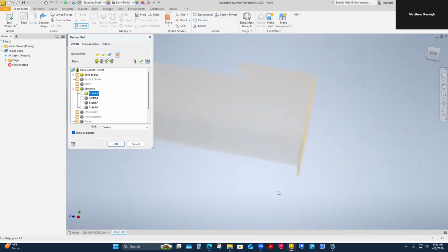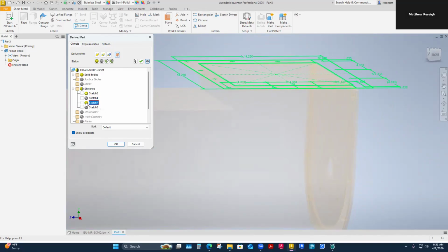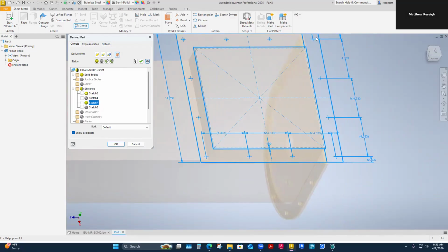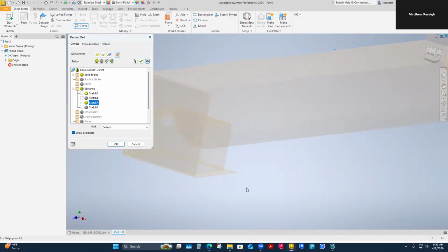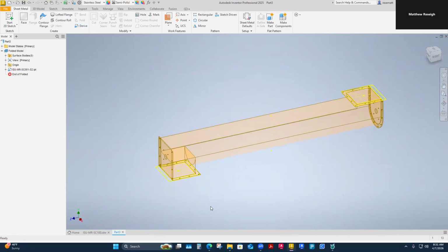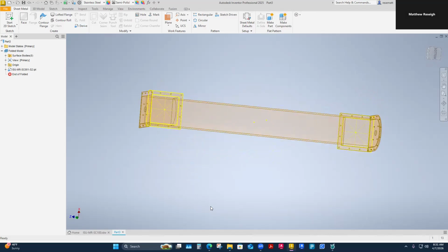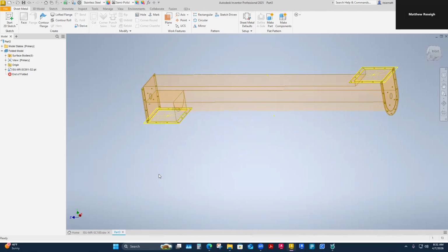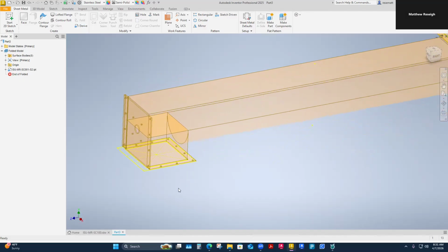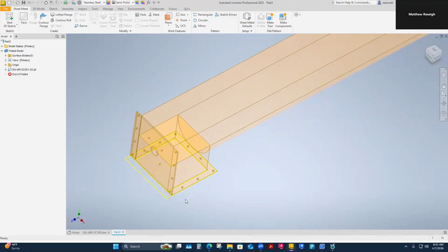I need the same thing over here because I've done the exact same scenario on this end plate, where it's going to be my fourth side to that flange. And so I'm just going to scroll through here. This is that sketch for me. And see, we already drew the hole pattern in, so it's just nice to use it. So I turn those two on. Yes, and then I'm just going to say okay, and this will come in with the surfaces and with my sketches. Of course, you can always get back and edit that derived part. So that's what's cool about that. If you didn't see that you needed this coming in, you can always get back into it.